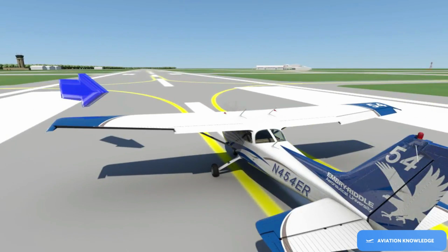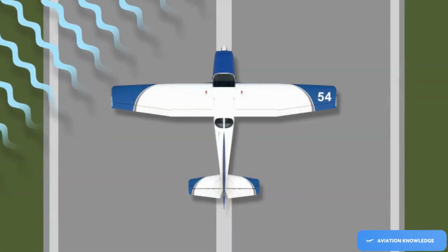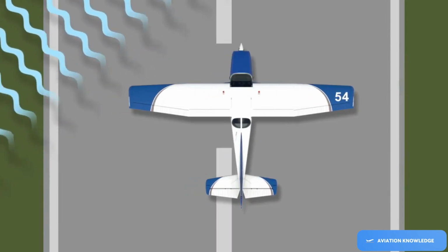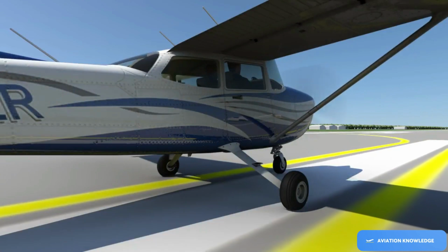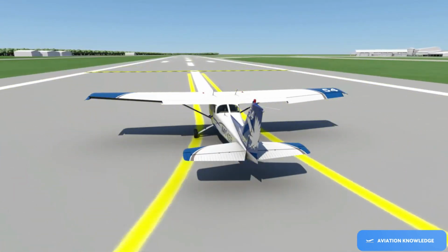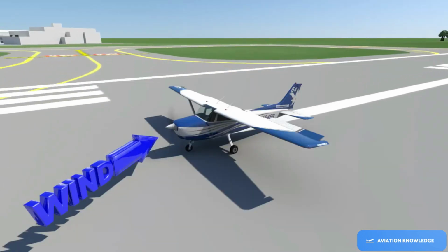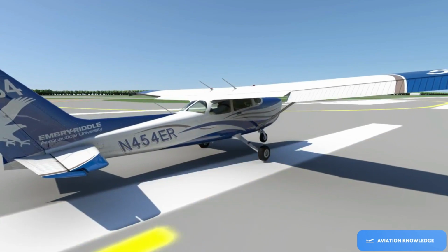Consequently, aileron input will be used throughout the entire takeoff. With improper crosswind correction, the airplane may begin to get pushed off centerline. This side loading causes stress on the landing gear, so it's important to use aileron correction throughout the entire takeoff roll.